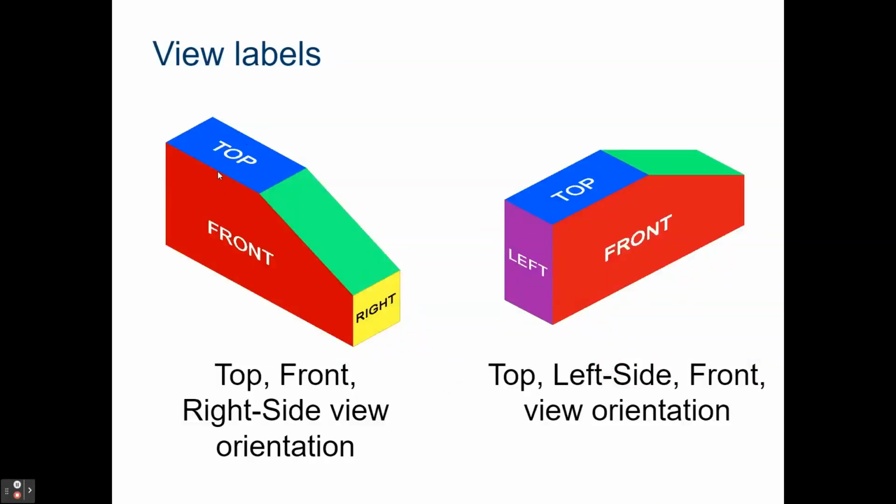Here you can see we'll have height, width, and depth represented equally. You can do a top front right or a top front left. Of course, we can do the back, the bottom, or anything else, but typically we always do a top front right side view for isometrics. The only reason you would pick left is if there was a particular feature there that you wanted to make sure that you drew out.